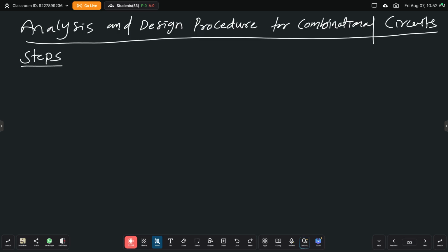When you want to use less number of gates, your Boolean expression must be smaller. Yes or no? When you minimize your Boolean expression, the technique is K-map. That is why we have learned it for 2 hours in the previous sessions. Got it? Right? Okay. The first step in this combinational logic circuit design is problem specification.